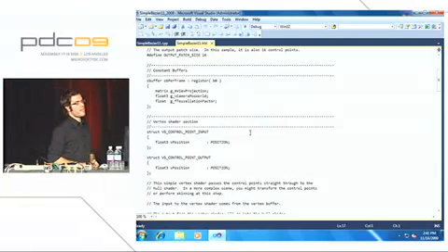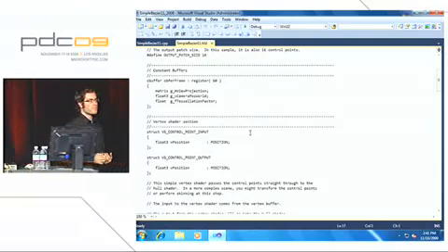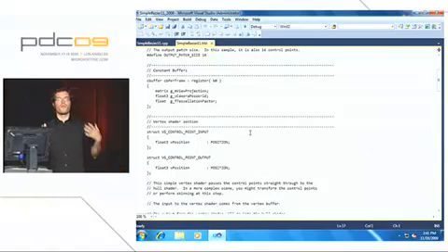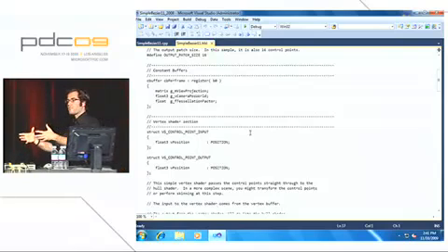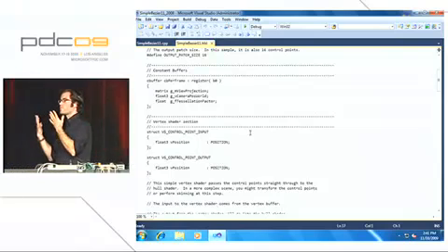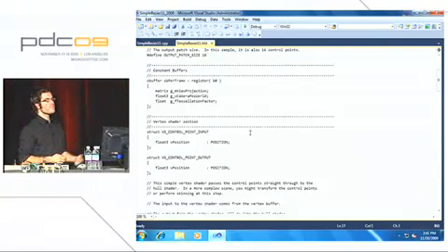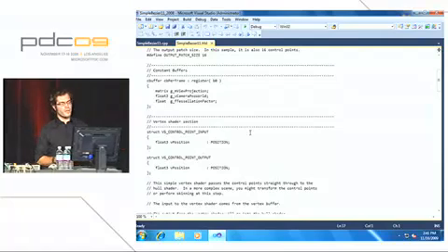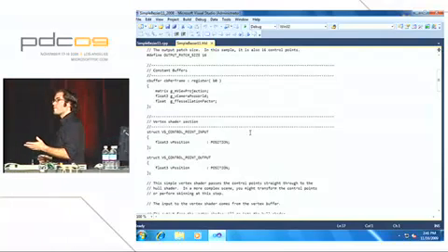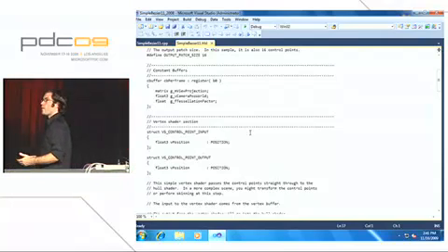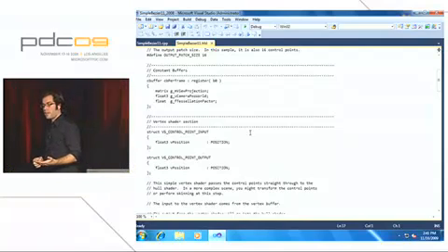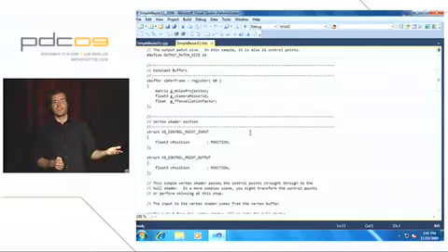And there are 3 variables that I actually use here. One is a matrix, which defines the actual transformation from 3D space of these patches into 2D space of the actual screen itself. So that does all the transformation itself. And then the next 2 values are some information. The next value is information about where the camera position is. And this will become useful when I'm trying to figure out the shading for the model later. The final value I have here is a floating point value that's called tessellation factor.